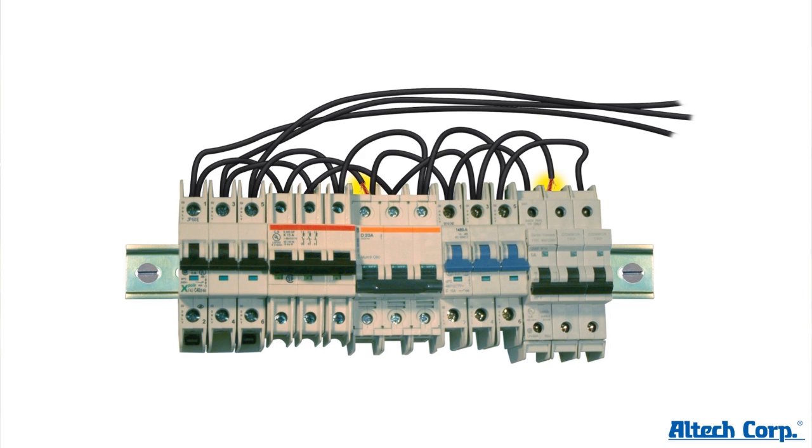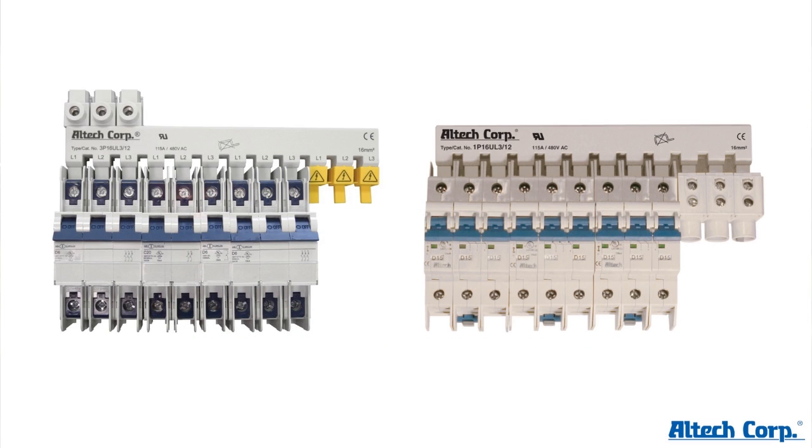To streamline that, in Europe, they use a bus bar. It's called a bus bar. It's essentially a solid piece of copper housed in a plastic insulation. The phases are insulated from each other, and you have a quick and easy installation there. Solid installation, no problem or no risk of daisy chaining, mixing wires, skipping a phase or anything like that. You pick the right bus bar for the right breaker application. You only install this once.